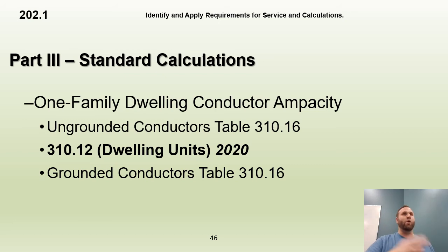If I'm over 800 amps, I can't use this rule, but because I'm under 800 amps, I can use this rule according to 240.4. So my next standard size breaker, 175. That means my main breaker for that service is 175 amps. That means I have 175 amp service. My total calculated load of that service is 165. My overcurrent protection device, or the size of the service, is 175.